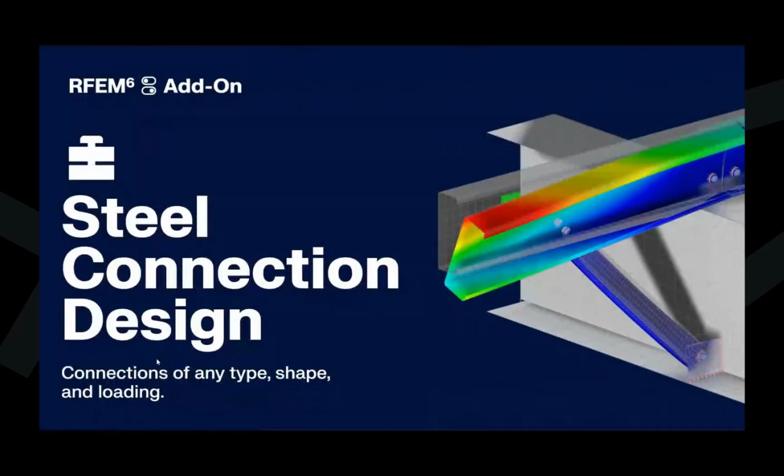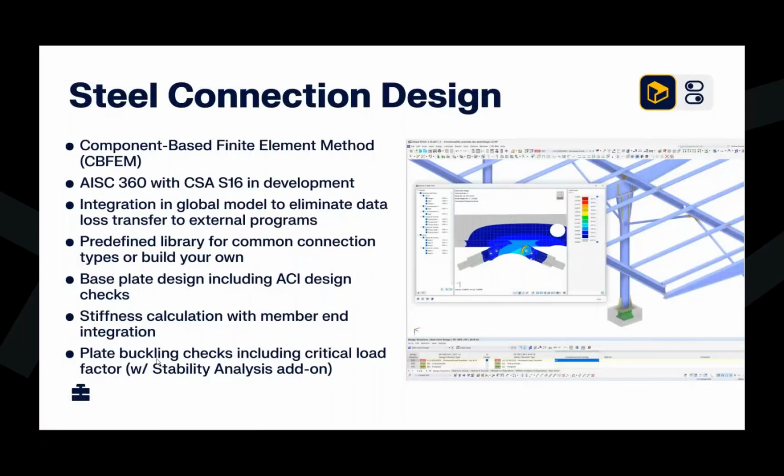On a related topic, we have our steel connection design. And this is certainly a bit more unique than a lot of the connection design programs out there. And the main reason is because we utilize the component-based finite element method. So for every connection, we are building up an FEA model underneath the hood. And why this is powerful is because this gives us the ability to design any connection. We're not just limited to the standard beam to column to brace.